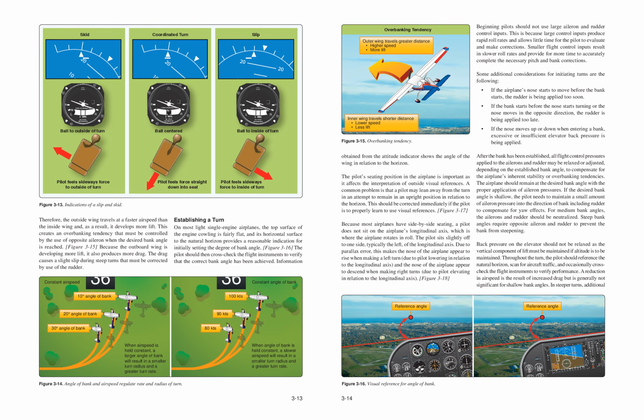Back pressure on the elevator should not be relaxed as the vertical component of lift must be maintained if altitude is to be maintained. Throughout the turn, the pilot should reference the natural horizon, scan for aircraft traffic, and occasionally cross-check the flight instruments to verify performance. A reduction in airspeed is the result of increased drag but is generally not significant for shallow bank angles. In steeper turns, additional reference angle